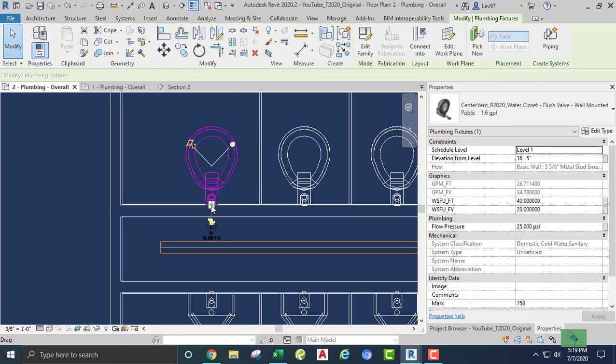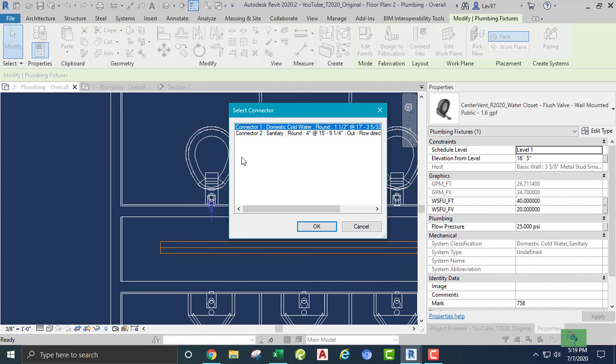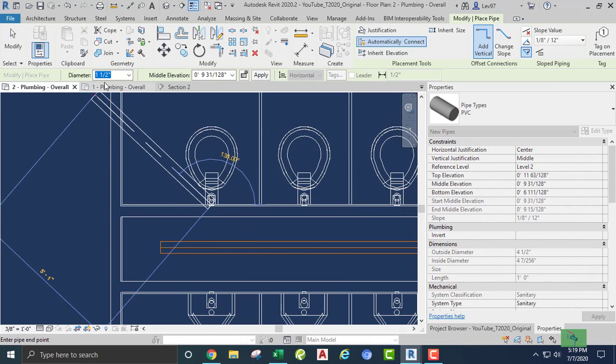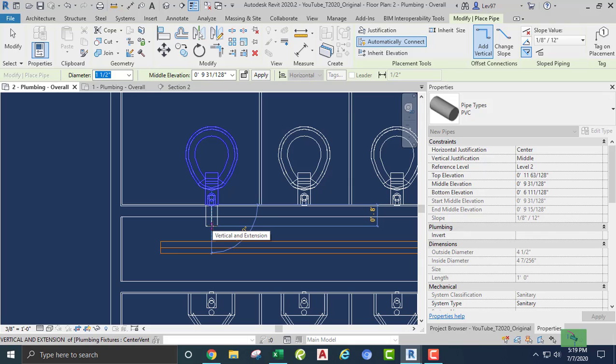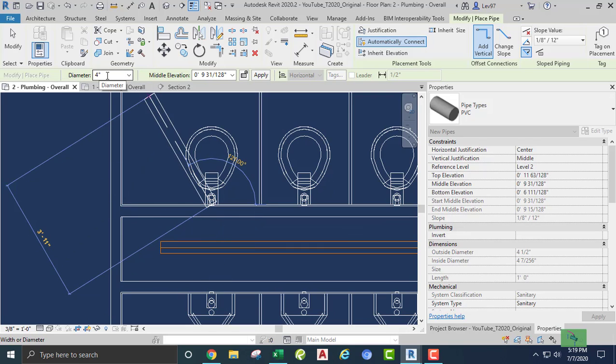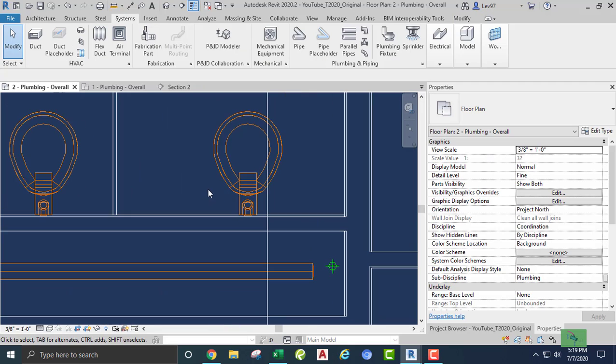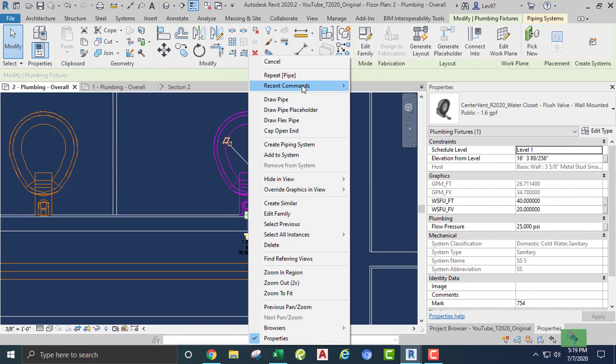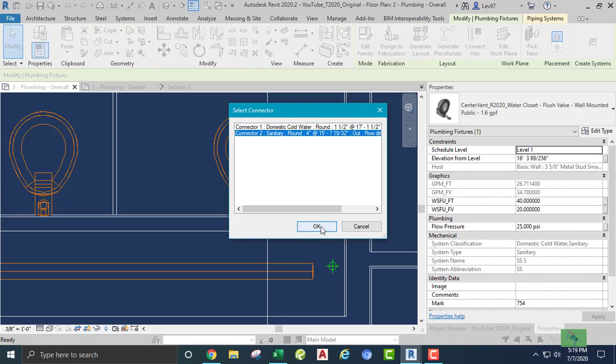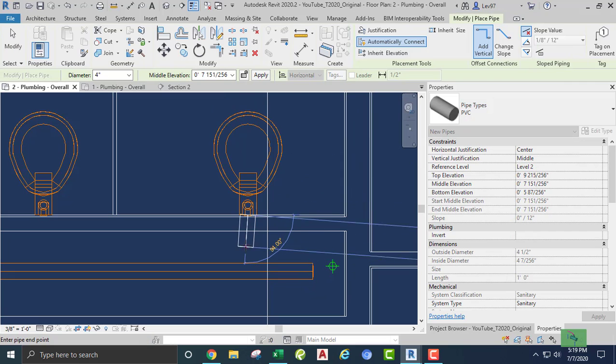So let's go here. Let's right click, draw a pipe, 4 inch. We're going to choose the 4 inch, right? And say okay to that. And Revit defaults to 1.5. And because it does that, I'm going to push my wheel, right? So when I push my wheel, it goes to 4 inches. Okay, and there's no slope, PVC, and we continue system type. I'm going to just leave that right there. Okay, so I'm going to go back. Okay, so now that we got that, go here, push, no slope, right, and go here.